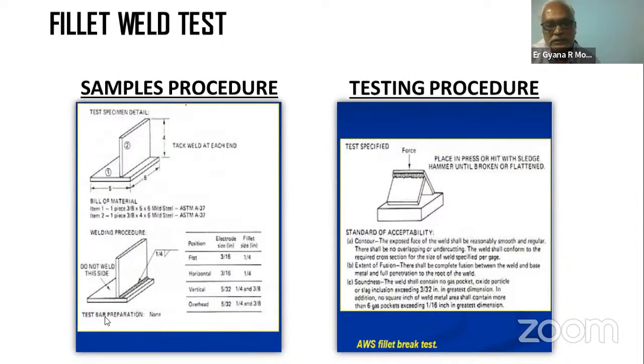So these particular testing procedures relate to the welding procedure specification sheet, and when you prepare a specimen and you do all these tests, then it qualifies that you weld with the particular parameters and with the particular consumable, and in the particular position it has been welded, has passed the test. And further, this is transferred to all welding procedure specification sheets, and every component is then welded as per the welding procedure specification sheet. And all these documents are supposed to be given to the inspectors at the time of inspection and passing the welds.